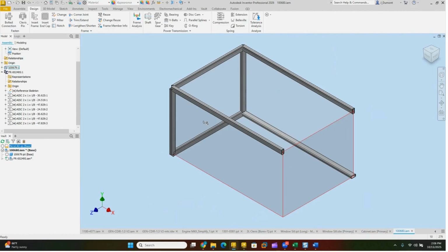Don't recommend it. Or there are ways of just using what they call Design Assistant. So if I'm trying to check an assembly in and I can't because of duplication, I have the ability of using Design Assistant to rename my files. I don't break the hierarchy, and then I can check them in and everything works fine. It just helps you to keep the clutter, keep the confusion